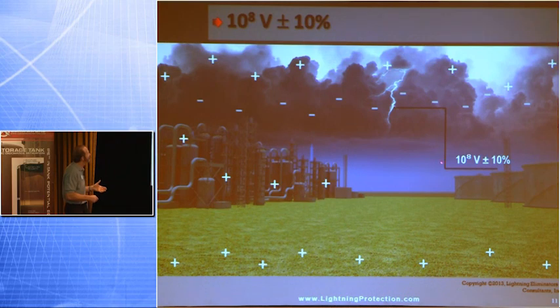If my field intensity is this pre-lightning strike, and now my air gap is only a couple hundred meters, now I've frozen in time, I've stopped the lightning bolt, so I can give you a slow description here. The electrostatic fields between the tip of that leader, the end of that lightning bolt, and the earth or earthbound structures have to increase. Same potential, smaller air gap, kilovolts per meter have to increase because my air gap's less.